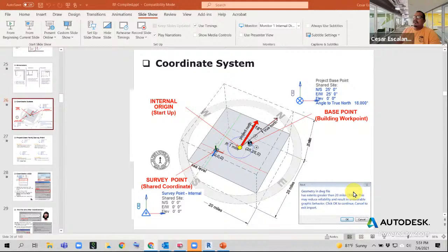An example is if you switch to a 3D view and things appear randomly, or you switch to a 3D view and you don't see anything, things disappear. Or if you render and the render is stuck or never finishes, that is an indication that there may be a CAD file that is creating a lot of problems.